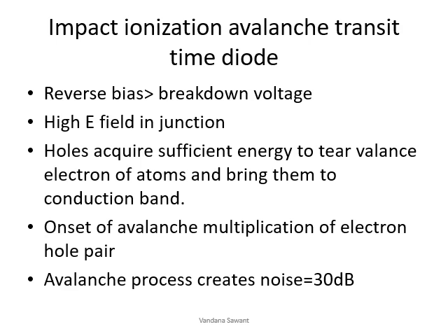If we give a sufficient reverse bias voltage to the device, then what happens? The electrons get energy from this reverse bias voltage and tear out the valence electrons, that is, the outer electrons of the atoms, and bring them from the valence band to the conduction band. If a large number of electrons are taken out of the valence band and sent to the conduction band, then suddenly breakdown will take place at the junction, and a large amount of current will flow through the device. That is called avalanche breakdown.